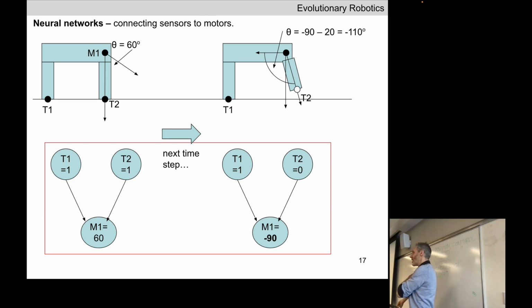It might start to fall over. So the front leg has come off the ground, which means it's now starting to tip forward. As the whole robot is tipping forward at this time step, at time step t plus 1, the leg has started to flex back inward. It's reverse direction, and it's coming back down again. So what's going to happen at the next time step? Or maybe the time step after that? The leg might hit the ground as it's moving backwards. The leg's going to come into contact with the ground again.